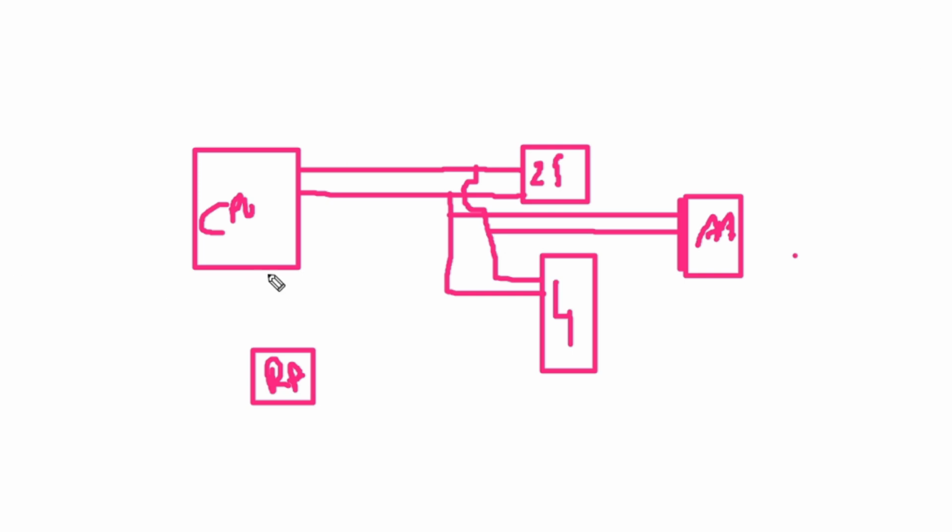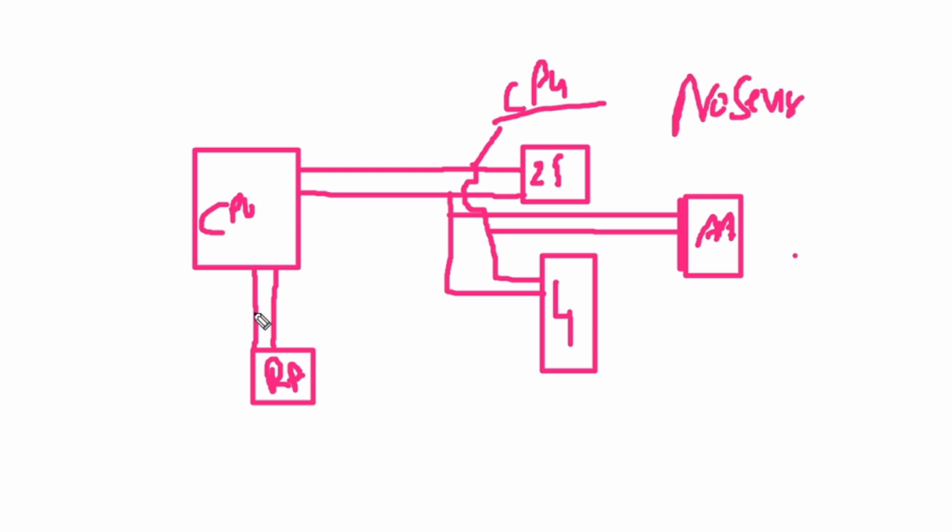But for your transceiver IC, it communicates through different lines directly to the CPU. Now, if any one of these ICs does not work, or is not connected properly to the CPU, or does not communicate with the CPU, no service is created. Also, if this RFFE line does not communicate with the WTR IC, the same no service problem is created.